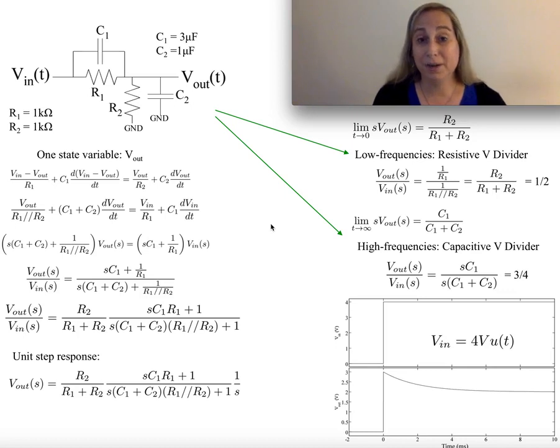So I want to talk about what looks, to many people, like a fairly straightforward RC circuit. And you think about the circuit and you go, well, this should be a pretty straightforward response. In fact, you look at the two R's and you think to yourself, this looks like a resistor divider at low frequency. That'll make sense. In fact, what we'll find as we do the calculations is that we would end up getting a resistor divider. And because the resistors are equal, the gain is going to be a half. And you think that makes sense.